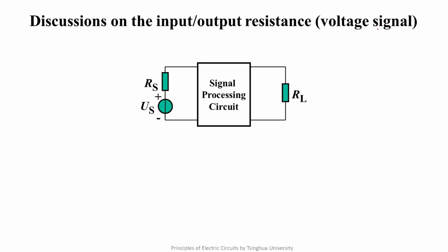In previous discussion, we always focused on the one-port network. Its input resistance is often called Req or Ri in the Thevenin theorem. It's the resistance of the network with resistors, dependent sources, but without independent sources, seen from the two terminals. It can be solved by the U2I method or by the I2U method.